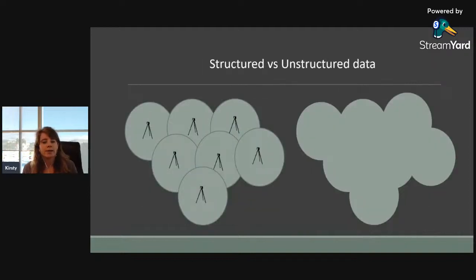So when it comes to point clouds, there's one key principle that you need to be taught straight away, which is structured versus unstructured. So what you can see here is a graphic I've made of 2 point clouds. On the left is some individual scan positions. With structured scans, each scan location, panoramic image and depth map is separate for each scan. It holds that information for each scan. But when you have unstructured data, you lose all of that individual scan position information.